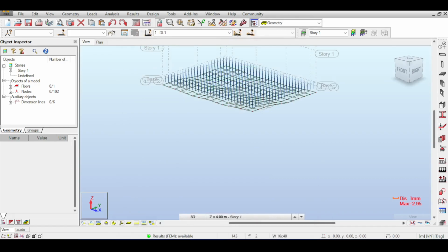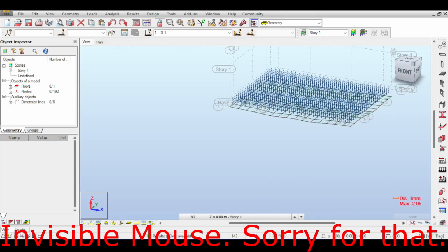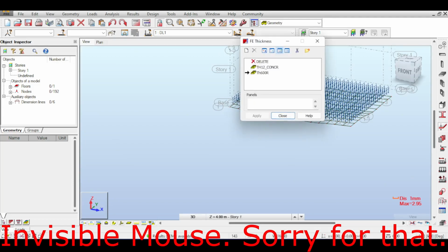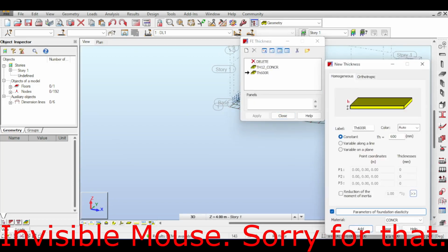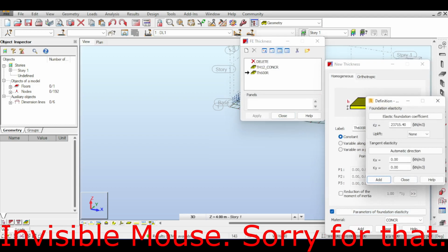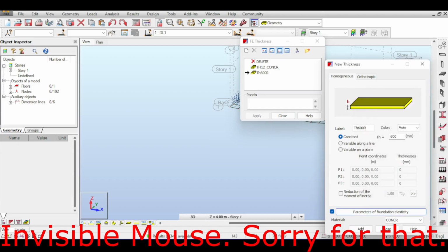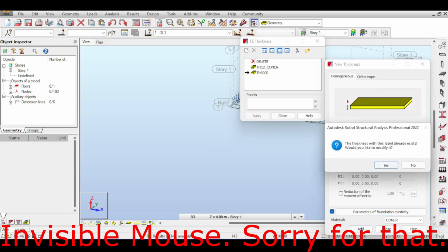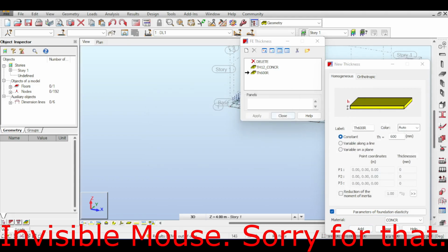Now, first of all, the instability in UX and UY is not dangerous because there is nothing pushing in the direction of UX and nothing pushing in the direction of UY. So to address the instability, you can go to thicknesses, which you defined there. Double click on this to modify the definition, and you can add some stiffnesses in the X and Y axis. I'm going to add 1, although I doubt that 1 is going to be enough to stop this. So even if it doesn't stop, I will not be addressing this too much right now.